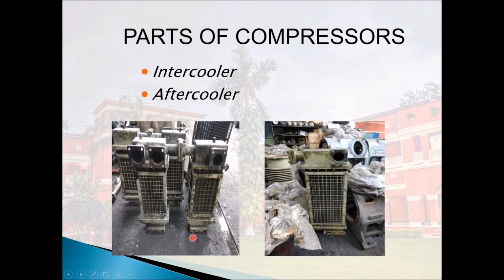Intercooler. The intercooler reduces the temperature of the compressed air, leaving the first stage prior to entering the second stage in order to improve the overall thermodynamic efficiency of the system. Aftercooler. The aftercooler assembly reduces the outlet temperature. It is made with external finned copper pipes.